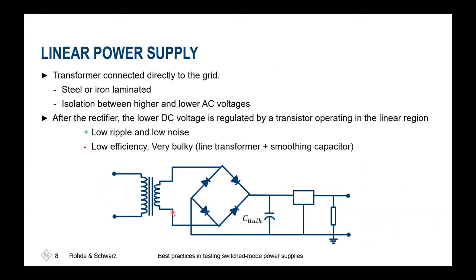Traditionally, we are using linear power supplies. So we'll have a transformer with a good old iron core inside. We'll have the diodes for rectification. And then at the end, we'll also have to ensure that ripple gets reduced, and therefore we have the circuitry next to that.